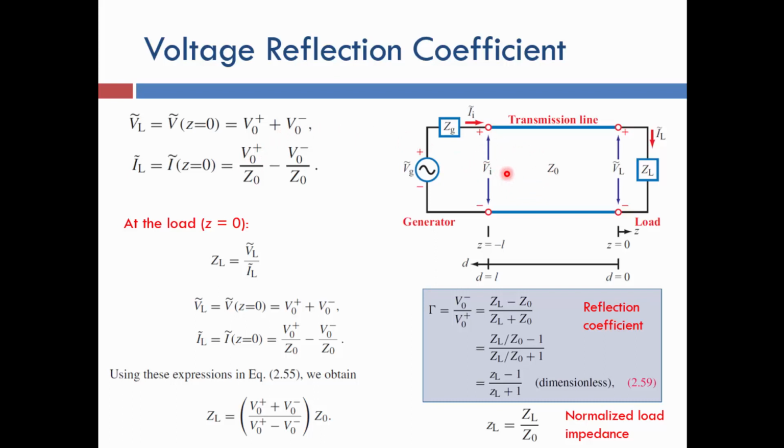So now if any two-conductor transmission line is connected with a high frequency generator and terminated by an arbitrary load, we have a system with a new impedance representing the ratio between the voltage at any point on this transmission line to the current which is measured at any point on this transmission line.